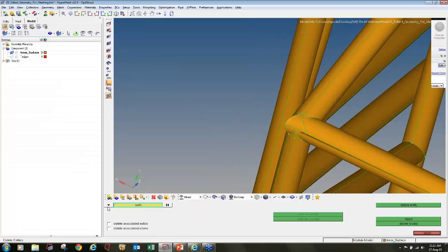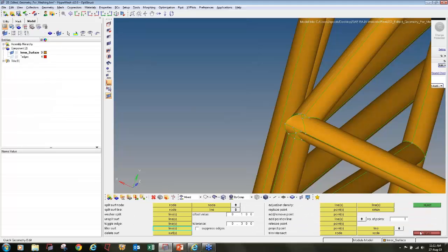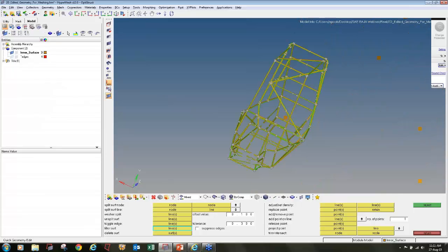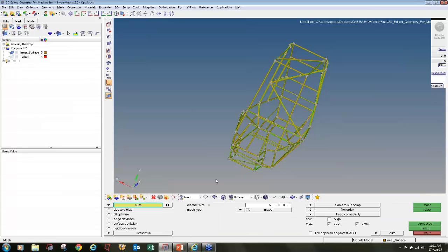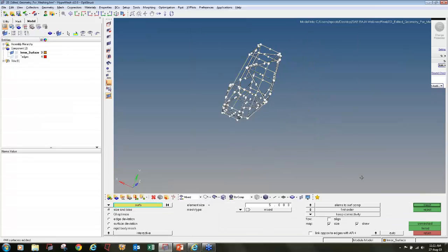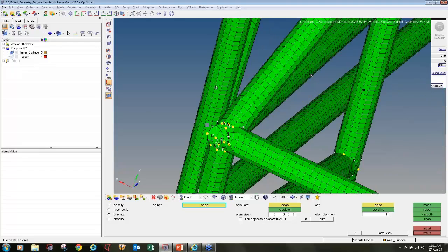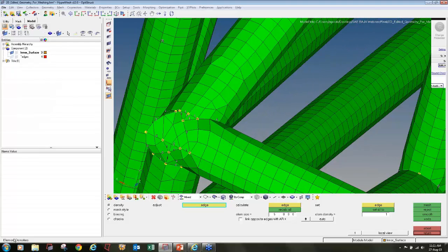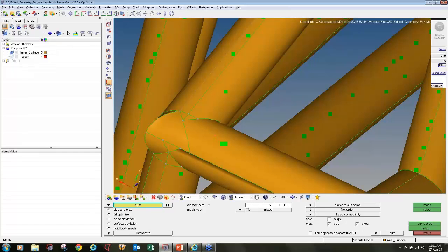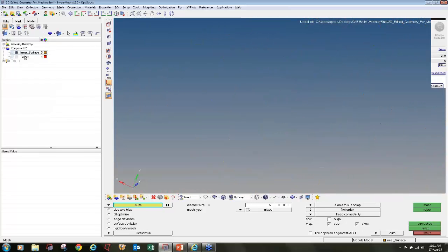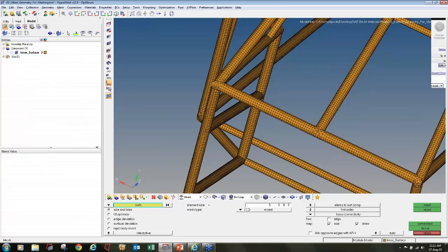So again I will do the meshing, element solve. First I will delete the existing meshing. F12 is the shortcut for 2D auto mesh. Select all the surfaces. Again I will do the meshing. So last time the problem comes here. It gives me the error. But this time there is no error, as I have already cleared that error which was coming. So I will delete this edge.